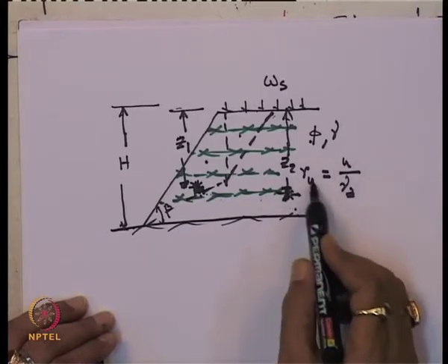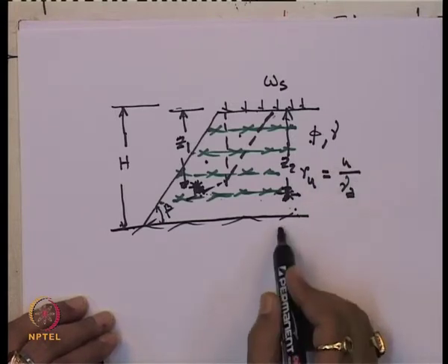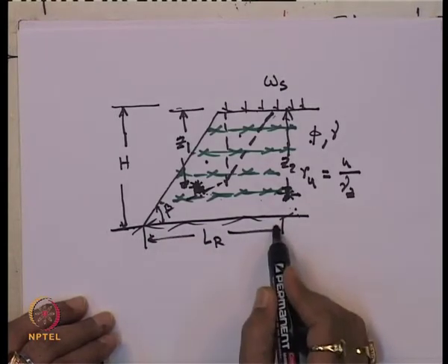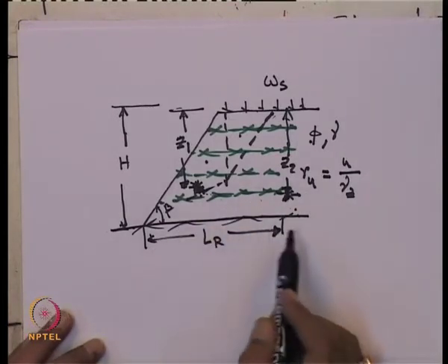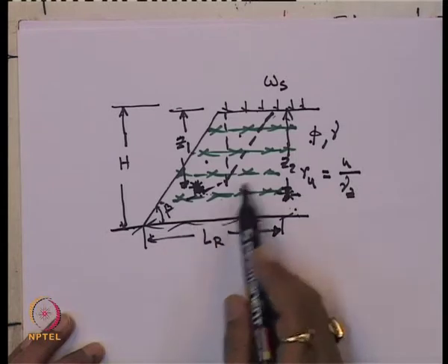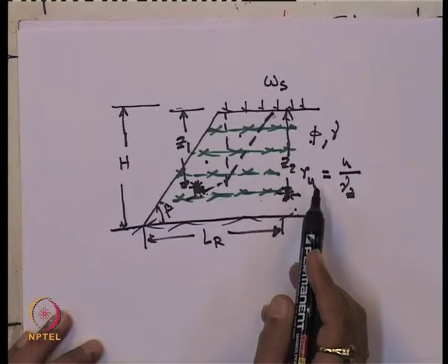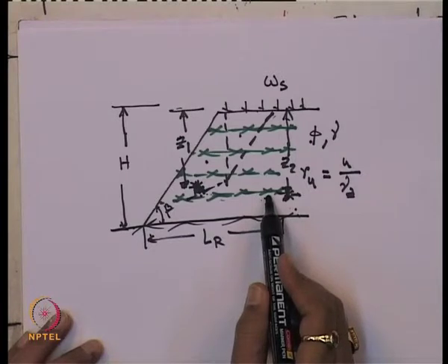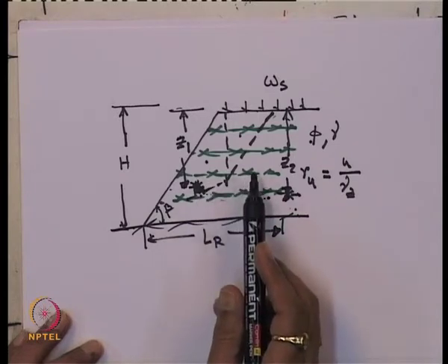Like this you can calculate the pore water pressure, and this is the length of the geogrid, let us say L_R. So, this is the definition for the analysis of a steep reinforced soil slope, given by Jewell in 1991. You can use the primary uniaxial geogrid material, or also the secondary uniaxial geogrid material.